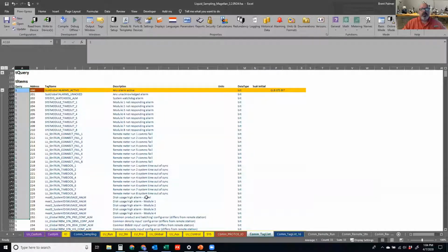So when I group something in query 1, I'm going to define its characteristics. I'm going to put the register size, the function codes that it can accept, and then I can add registers into it. And we have to follow some basic Modbus rules when we're doing this. If I'm a slave, then I can put an unlimited number of registers inside of a query. So I can create all these registers, and they're going to follow by this one set of rules. But if I'm polling something, then I'm bound by the maximum size that a Modbus master poll could be, which is 254 bytes.